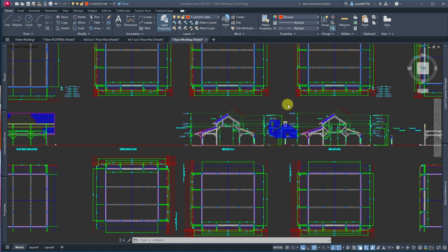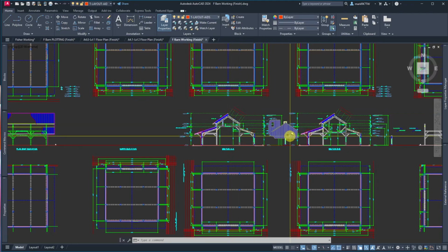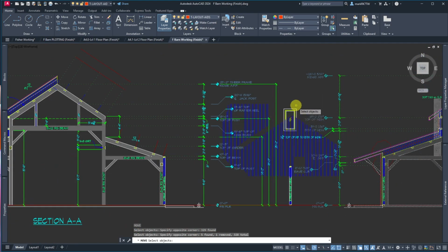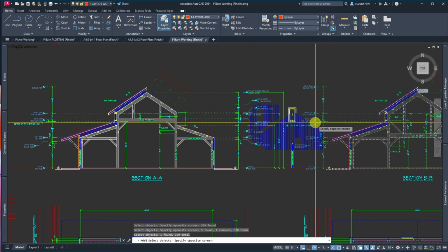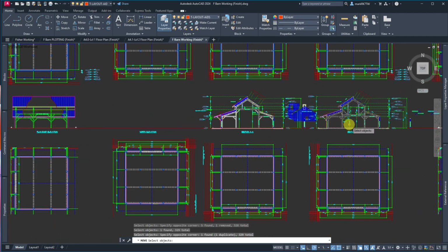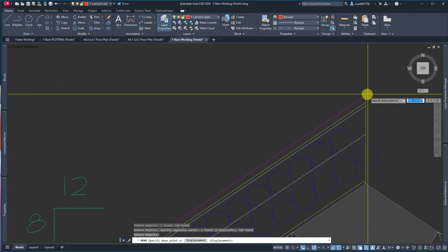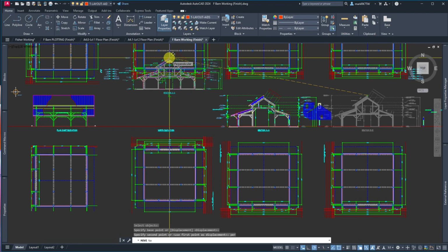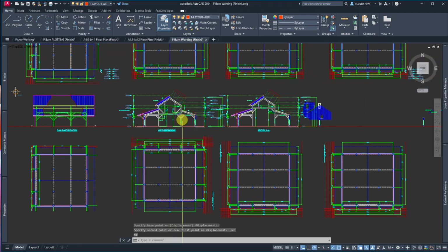So if we're doing the rear elevation, I'm going to copy this one because it's got the bent that has the low loft floor, which will be what we see from the back. And I can tell you this one is not rotated yet because the door's on the wrong side. So we're going to first just copy this whole guy there, but I don't want that window, any parts of that window. I do want this dimension. I don't know why, because it's elevation. I probably won't need it. So I'm going to copy it from this point, and I'm going to go perpendicular to that ridge. And you'll see the line appear down here. There it is, bink, and it drops right in there. Got some crossover. Stuff's just too tight.